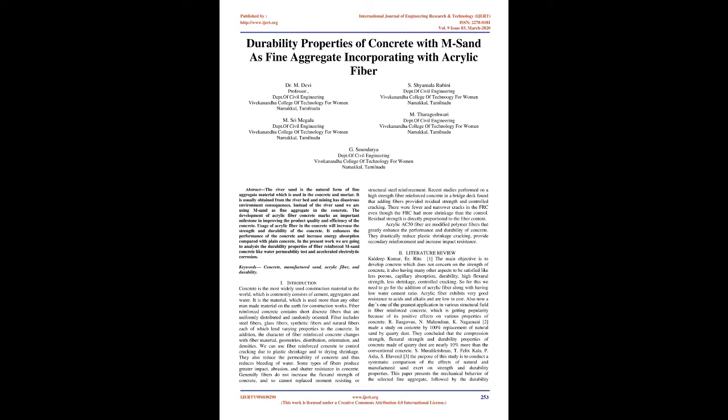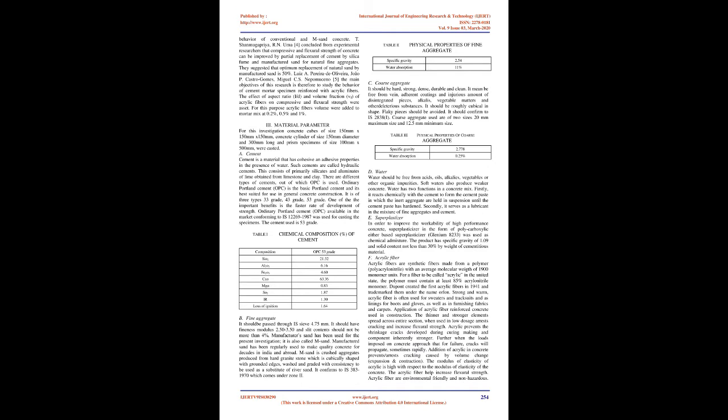For this we need to go for the addition of acrylic fiber along with a low water-cement ratio. Acrylic fiber exhibits very good resistance to acids and alkalis and is low in cost. Also, nowadays one of the greatest applications in various structural fields is fiber-reinforced concrete, which is getting popularity because of its positive effects on various properties of concrete.